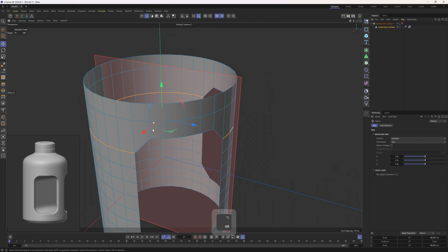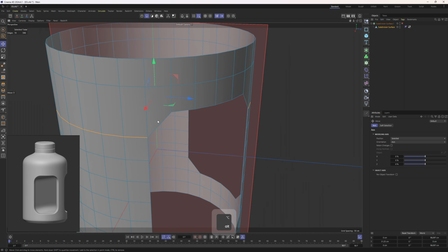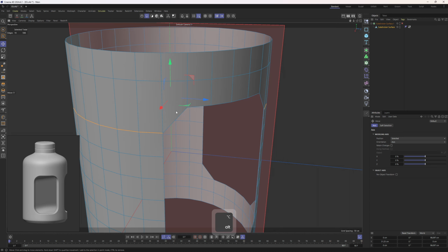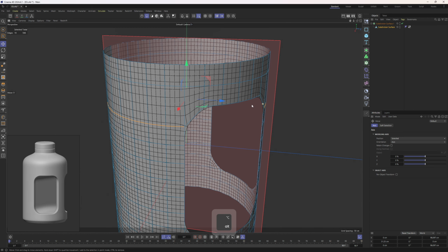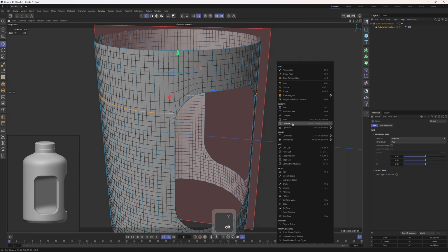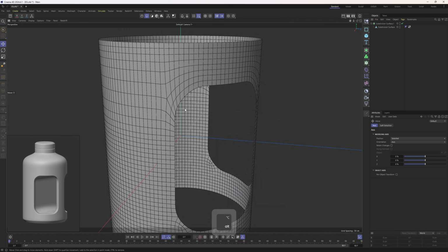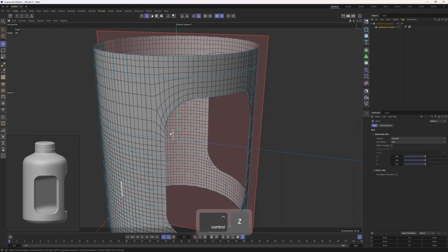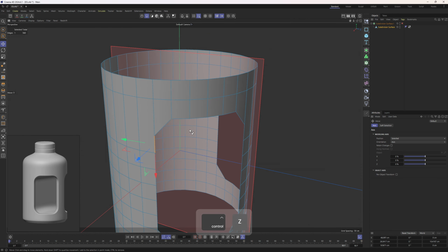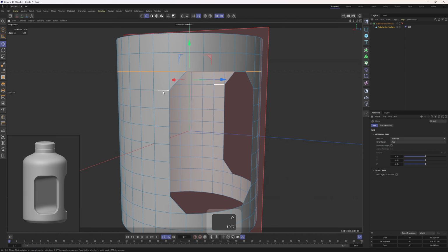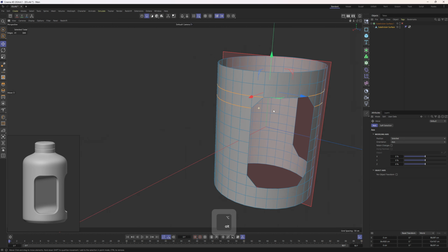I know this is going to sound and look weird, but just look at the flow. I will first enable the subdivision surface, then dissolve out these edges. And here we go. Now the flow is going with the detail, with the roundings. Ctrl Z, I'm sorry, I made another mistake. First, I need to adjust these roundings.